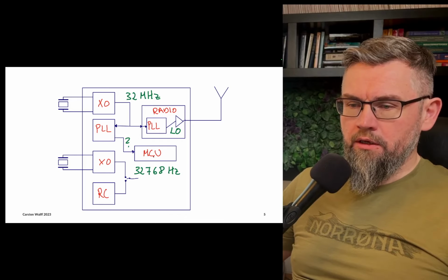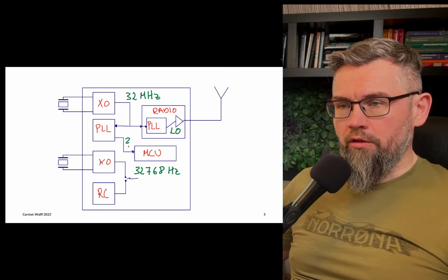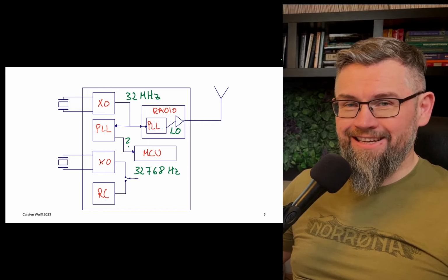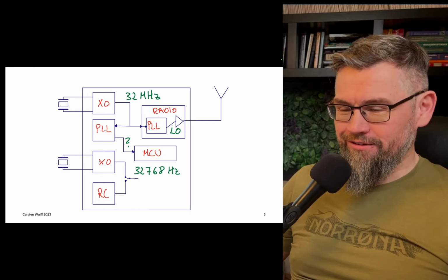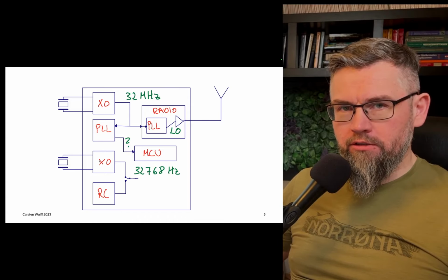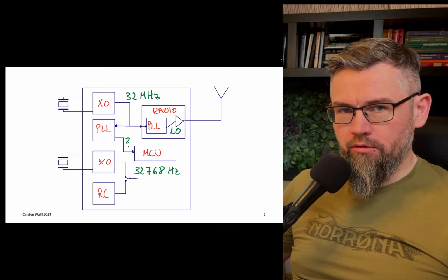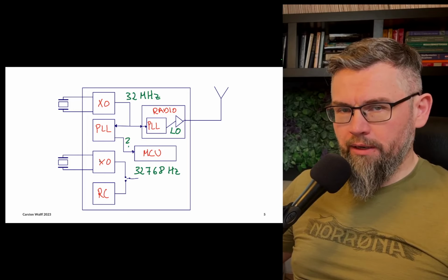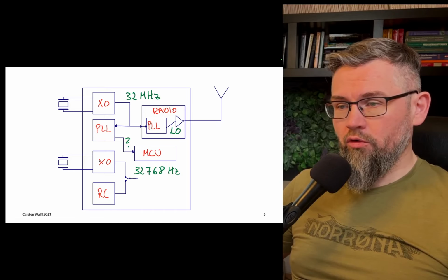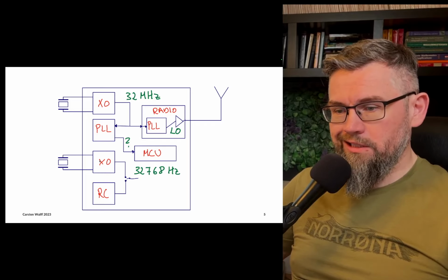Now the low frequency crystal, that's often used for sort of real-time clock. The fact that maybe you want your device to sleep for a second and then wake up precisely at 1 second later. And this is used in Bluetooth communication, where when you're in connection in a Bluetooth system, you actually schedule when in time you're supposed to wake up and listen to the radio or listen for packets and transmit packets. Those are scheduled events, which allows Bluetooth to be low power, because you can turn off the whole chip and just run this real-time clock and then wake up precisely when you need to.